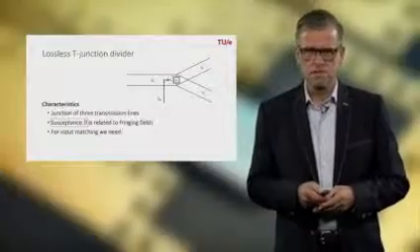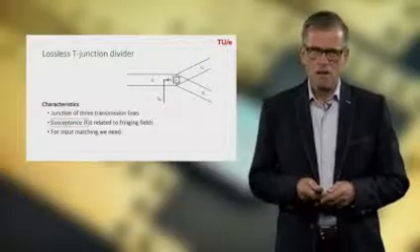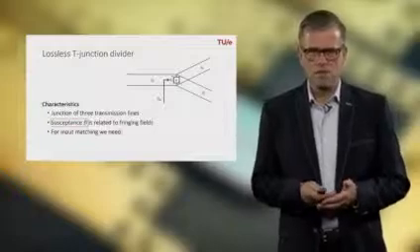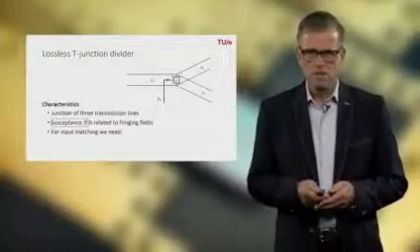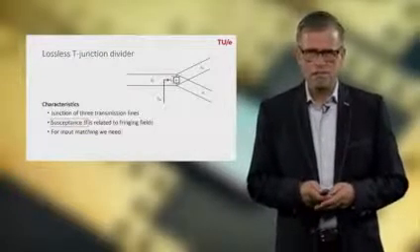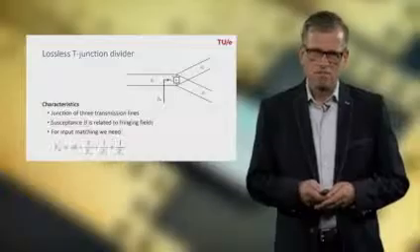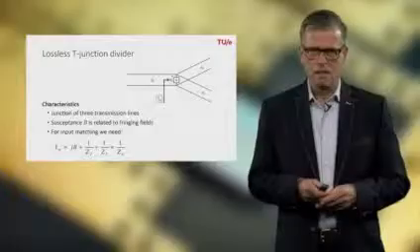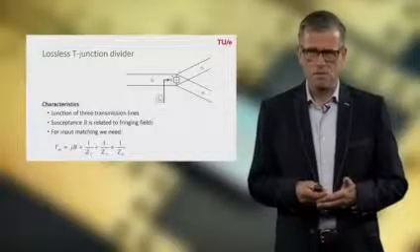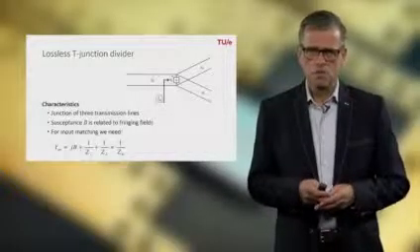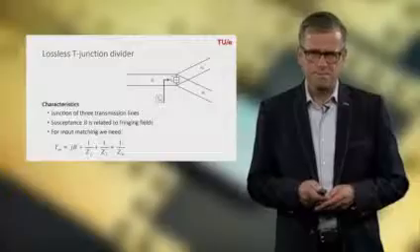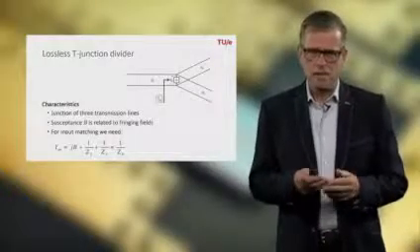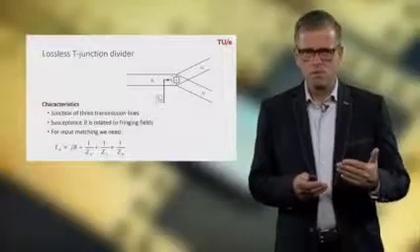Now, if we would like the input of this power divider to be matched, then the input admittance, which is shown in the diagram here, which can be calculated from a parallel connection of the susceptance and the 2 output transmission lines, as shown here, should be equal to the characteristic admittance of the input transmission line.